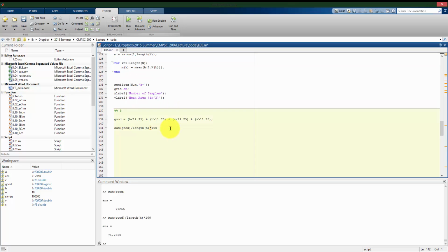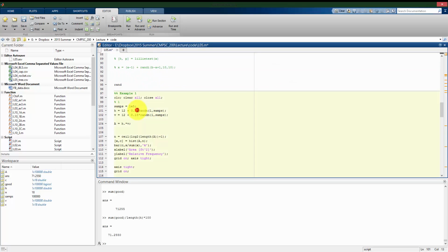This does answer part 3, but let's redo this a little bit. So I'm going to go back. Let's say that I improve my equipment and it's able to make cuts with a smaller standard deviation. So let's say I can reduce my horizontal cut, instead of 0.2 inches as my standard deviation, I can halve that to 0.1. And for my vertical, let's say I buy a new saw and it does a better job, and that's also at 0.1 here.